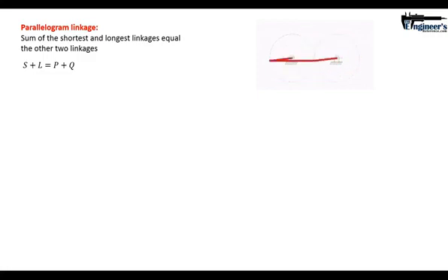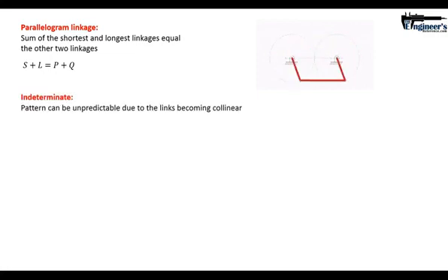There's actually something to this particular design that is very curious. Its motion can become indeterminate, or another way of saying unpredictable, when the links are collinear. Now what collinear simply means is when all these linkages completely line up, and they completely line up when they're in the horizontal in this particular orientation, and that lineup is called a change point.